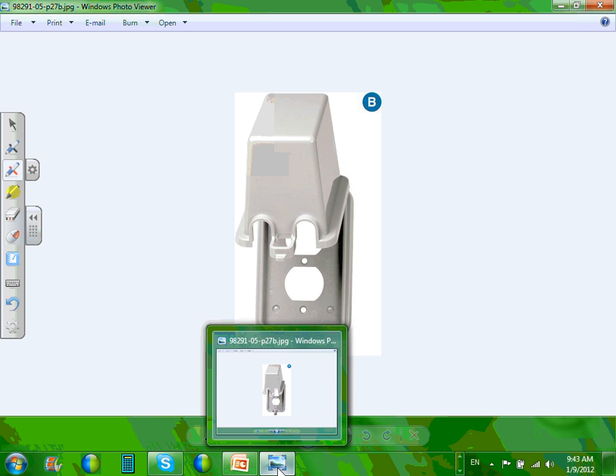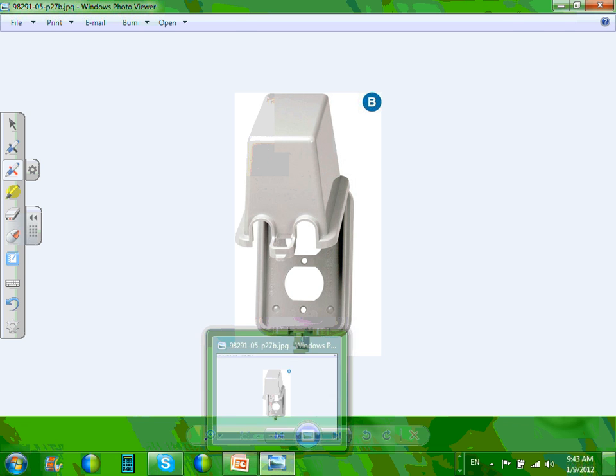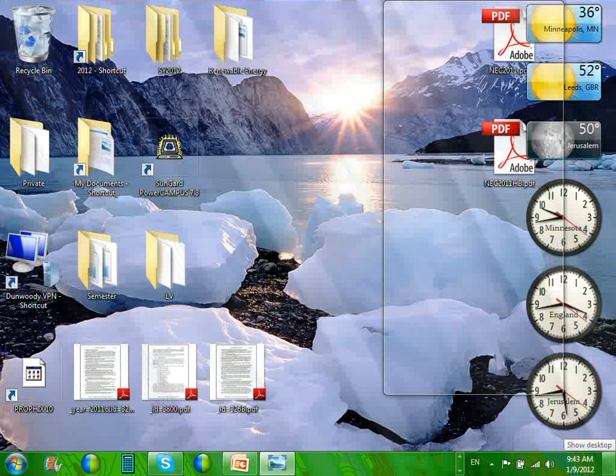Let's look at the slot. If I have a 15 amp load, can I plug it in a 20 amp receptacle? Yeah, bring it on. The other way is not true. A 20 amp load, can I plug it into a 15 amp receptacle? No. If I have a 20 amp microwave, let's say it's industrial quality, you can't plug it into 15 amp. No, I know I can't. But if I plug it into a 20 amp receptacle, haven't I just broken the rules?